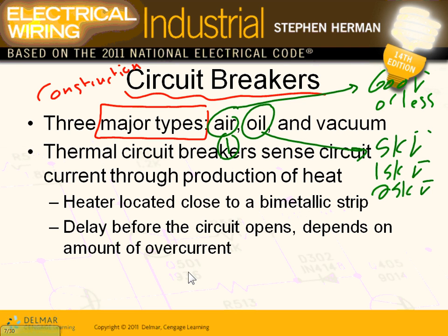And also vacuum tubes. For the most part, vacuum tubes, they have a tube, and they remove all the air from the tube, and they put the contacts inside the tube. You're going to look at them, guys. And if there's a short circuit, it will interrupt the short circuit in a tube that has no air in it. Anybody knows why no air? If you have air, every time, guys, you interrupt a 4,000 amp in air, the amount of energy that you're interrupting will ionize the air and make the air conductive. So momentarily, the air will become conductive, and you have a big arc coming out of your contacts.